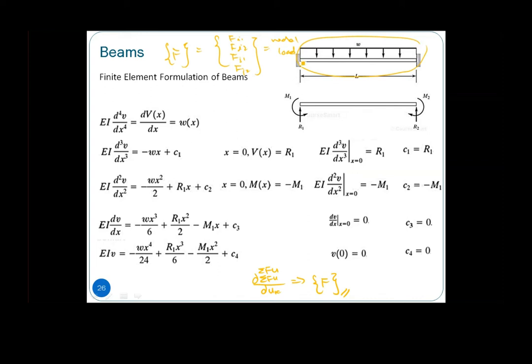Okay, so from here, let's say I have a distributed load. How can I find the equivalent, how can I convert it to the loads that are equivalent at these two nodes? We can use the minimizing methods, or we find what we call the reactions at the supports, these two. By taking the opposite of this reaction force and the moment itself, we get the rotations as well, the loads applied at these two nodes, UI1, UI2, UJ1, and UJ2. So that gives us FI1, FI2, FJ1, FJ2.